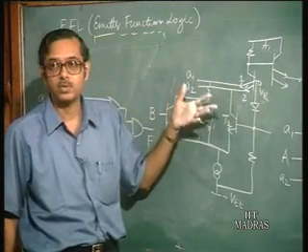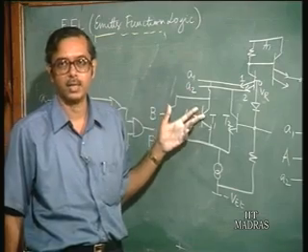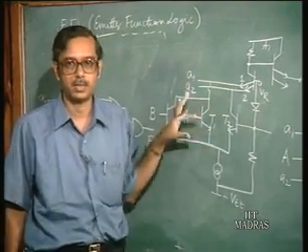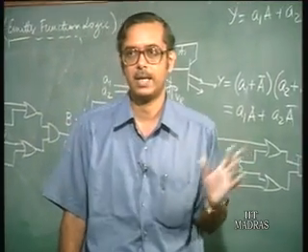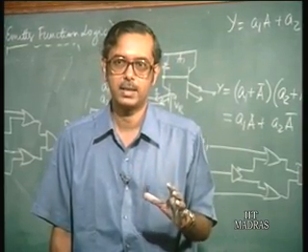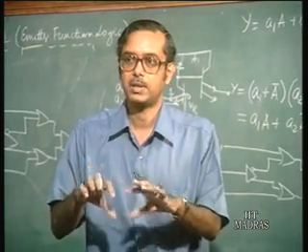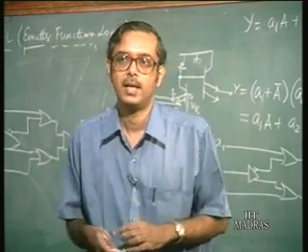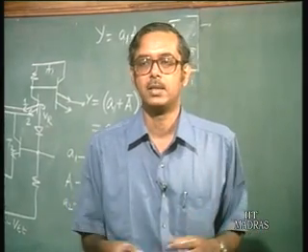That is, we have removed the emitter followers. So, whether the circuit will actually work, because the voltage levels are different. So, what are the voltage levels required to make this circuit work? These are the things we shall see, but of course, we can see that the functionality is improved tremendously in this circuit. That is, you can make a lot of complicated circuitry using the same power consumption as in a single gate, and that is why this is called emitter function logic, and it is an important variation of the ECL gate for low power dissipation.